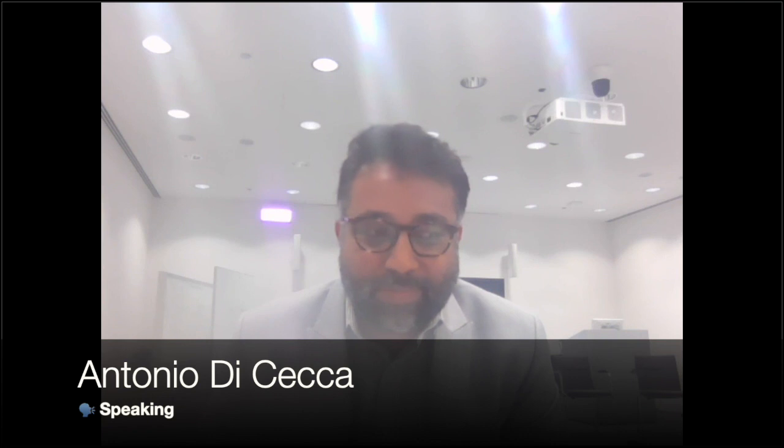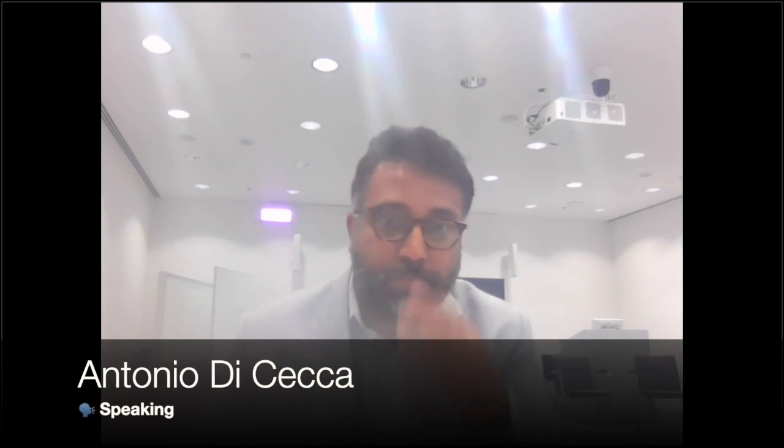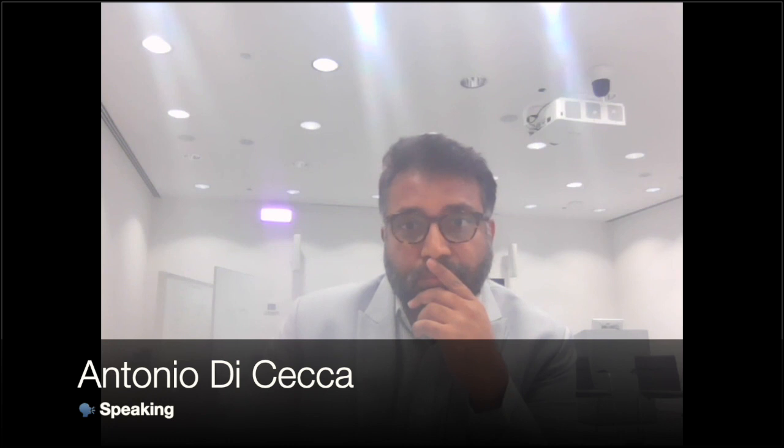Sorry, I didn't want to cut in, because I have the audio at a different time from the video, so it's not easy to follow. I was just going to say that B2C and residential are part of the customers, because one of the advantages of district cooling is the diversity. Why is district cooling interesting in terms of cost and economy of scale? Because we benefit from the diversity of customers and different profiles, and this requires less capacity to be installed, because residential demand is different from office demand. When people are at the office, they don't consume AC in their houses. So we can use this diversity as an advantage to reduce the cost of the district cooling system and transfer this cost reduction to the customers.